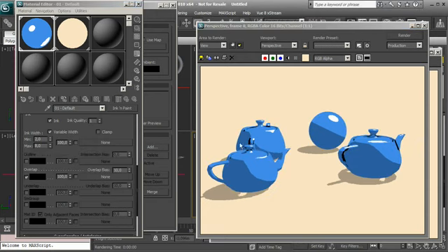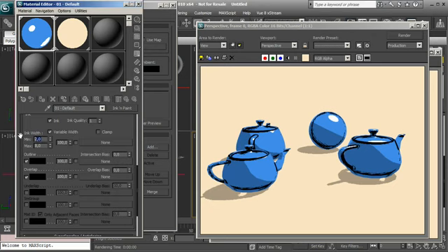Then we have the overlap. So we have just the faces where the edges are overlapped, we are using the ink, and you can use, like always, the texture, and you can decide the overlap bias. So we can change it, and you see that we are no longer using the overlapping area, and there we have the usage for all the overlapping area. And it can be interesting because with this one we can use, for example, 0.5 and 4 for the ink width variation, and we can achieve a very interesting look, because you see that it seems it was traced by hand, and it's a very, very interesting look.